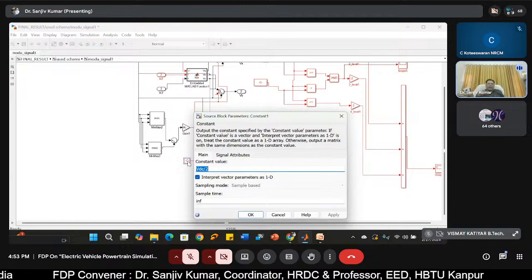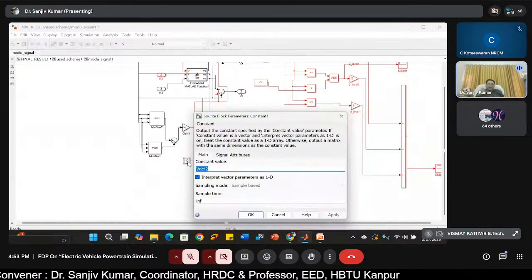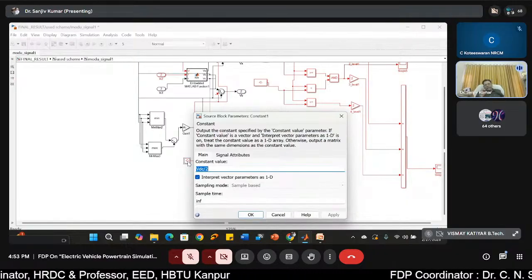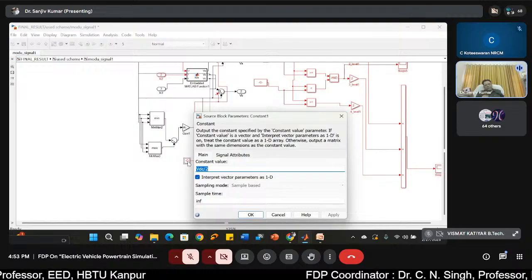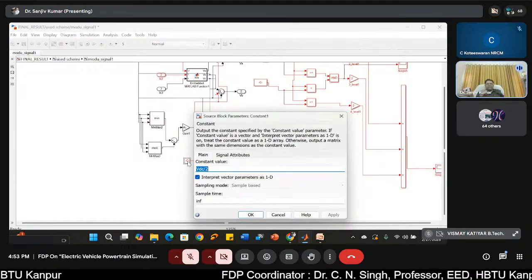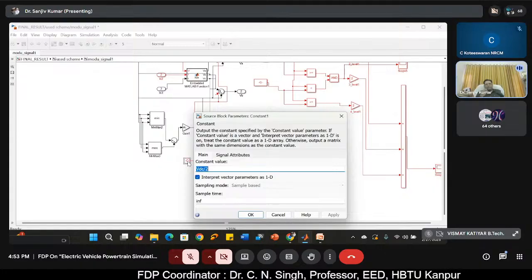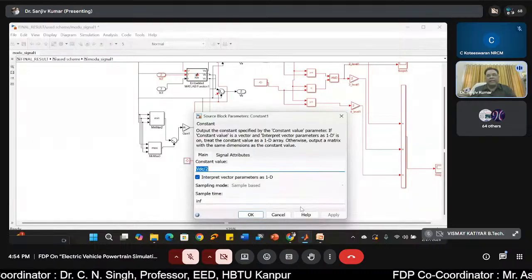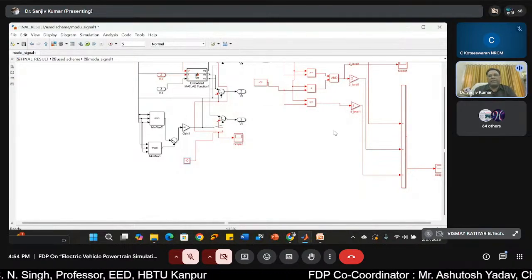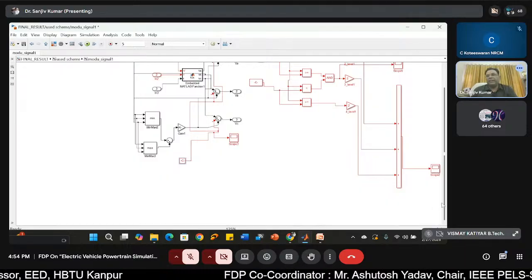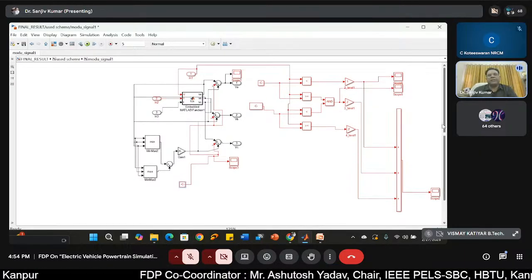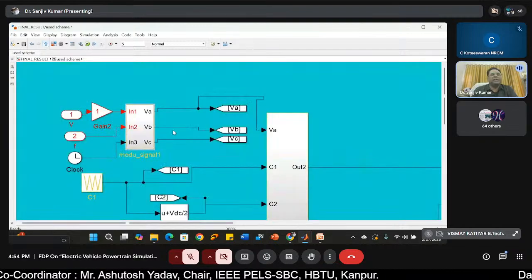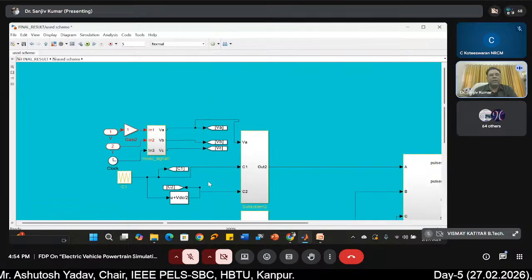Now, if the amplitude of the reference voltage is plus minus VDC by 8 up to that, then the sine wave must be put at the lowest angle. The moment it is increased from VDC by 8, half of the VDC by 8 is to be added. Likewise, this is the philosophy we have adopted, and the modulation signals are generated. I'll run the simulation in the end, then these things would be more clear.